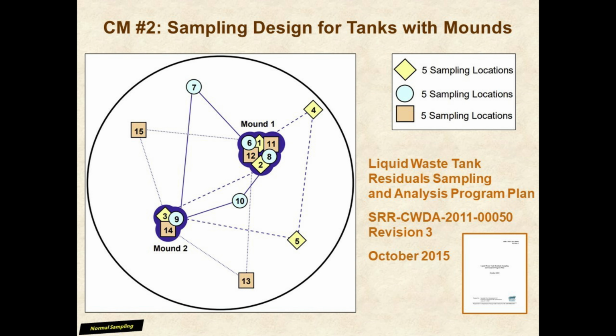The robotic crawler will collect 6 samples from the relatively uniform bottom layer, with 2 increments going to each of the 3 sample arrays. Although the mound and bottom areas each contribute 6 sample increments, the final masses apportioned to the ISM sample will differ due to volumetric proportioning as discussed in parts 1 and 2. Because the bottom layer contains more volume than the mound, the 2 bottom increments will contribute slightly more mass to the ISM sample.